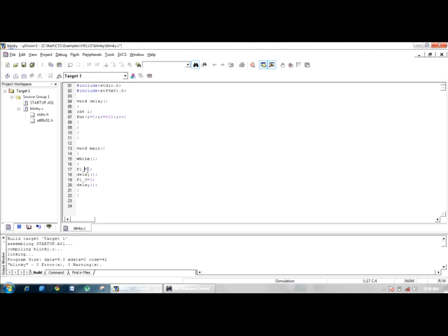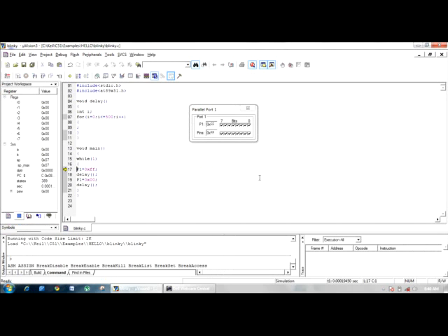Now click here, remove this pin specification. This means that port 1 as a whole we are specifying as 0xFF, hexadecimal FF, which means all the pins are high. Port 1 is 0x00, hexadecimal 00, which means all the pins are low. Now click save. Again build, translate, build and rebuild. Click debug, give OK. Now the port 1 appears. Now click run, see what happens. The total port is blinking. So this is how you are going to use port 1.